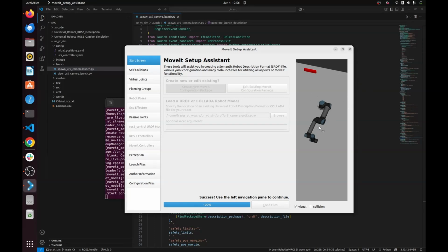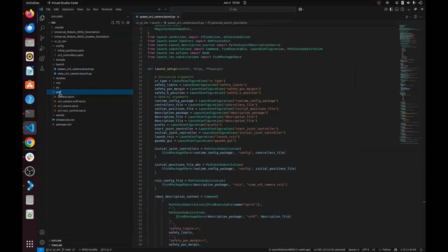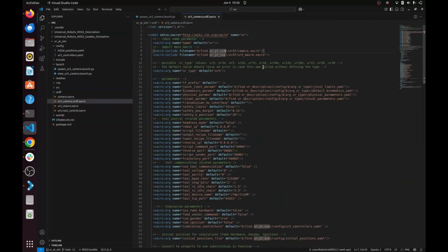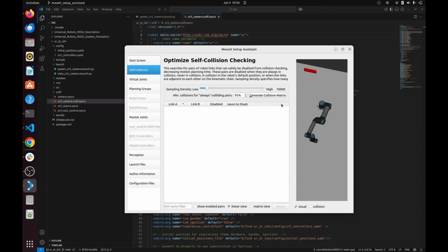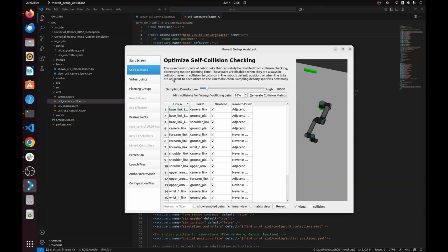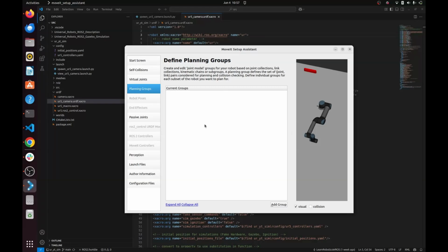And again, if you want to make MoveIt Setup Assistant work, the most important thing is that in the robot model description you put a name, whatever it is going to be. I've set up universal_robot. By default, this points to arguments, but if you do that, I remind you that MoveIt Setup Assistant won't work. Okay, so here let's set up self collisions. Virtual joint, we do not have virtual joints.